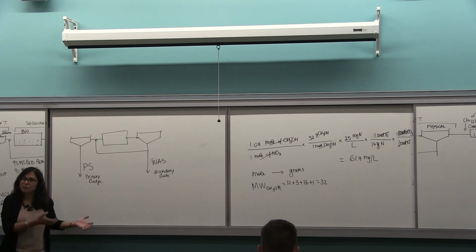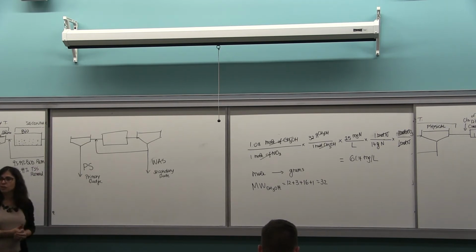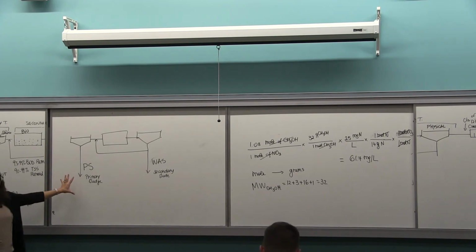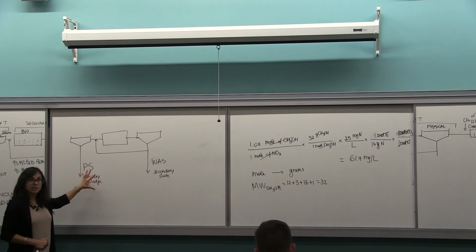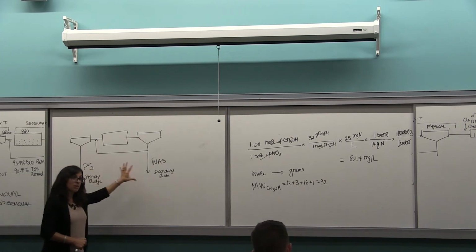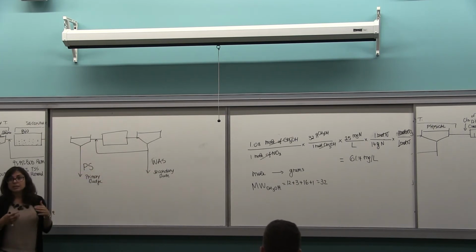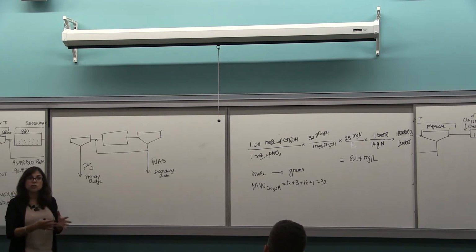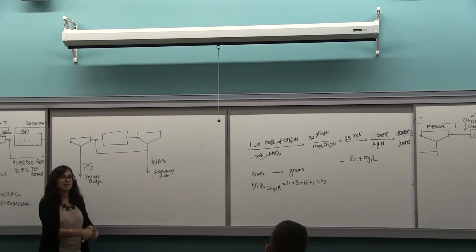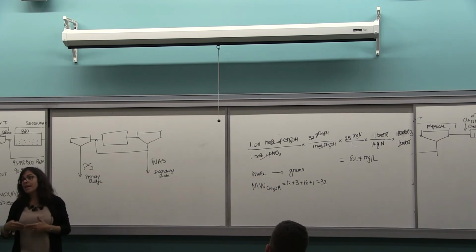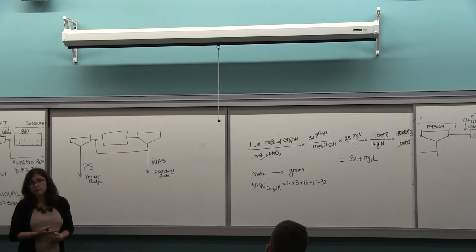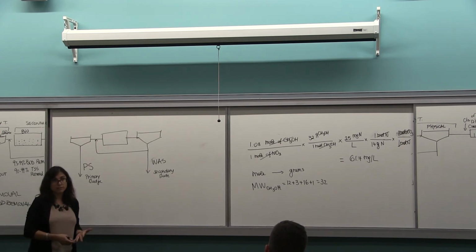So it's not very convenient to truck out all these gallons and gallons of water. But also, it cannot be disposed without further treatment. So sludge treatment needs to stabilize, remove the pathogens in primary and secondary sludge, take all the water out so that you can have a solid that can be moved in a truck and disposed either at a landfill or at an incinerator.